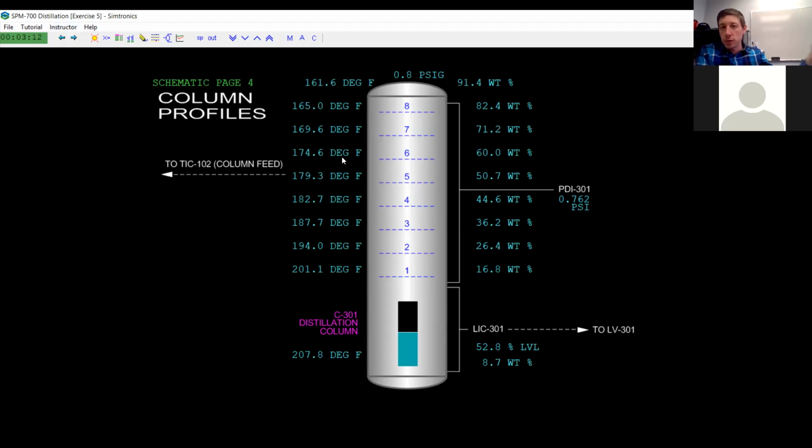So now we're getting alarms. That stuff is not operating the way we want, after just 2 minutes. Now we're all the way up to almost 1 psi, which is going to drastically change the point at which this material boils. Our hexane is no longer boiling at 156 degrees Fahrenheit. It's going to boil at a higher and higher temperature, which means the concentration of hexane throughout the column gets higher and higher, to the point where we're sending it out with our bottoms product.